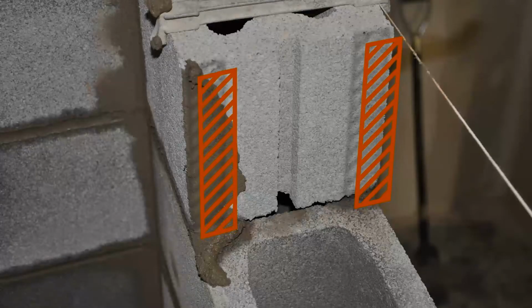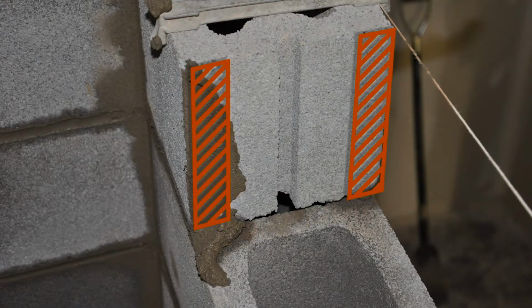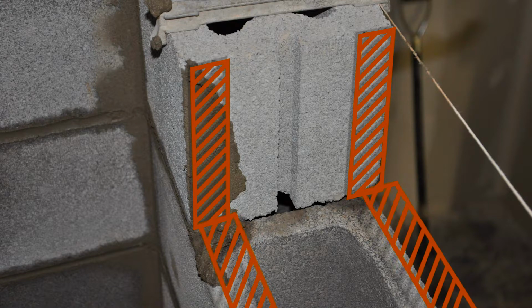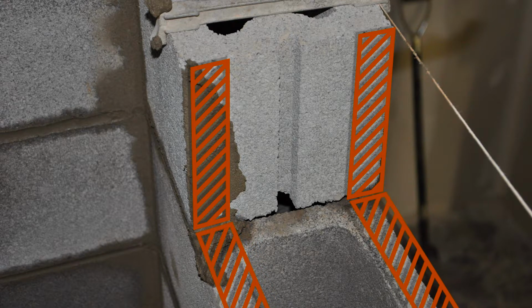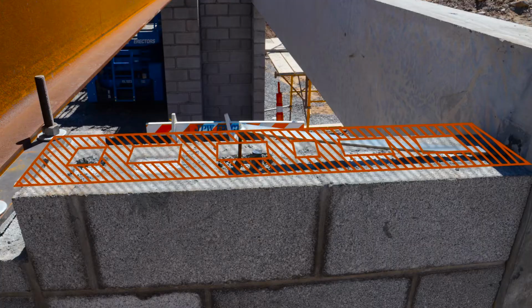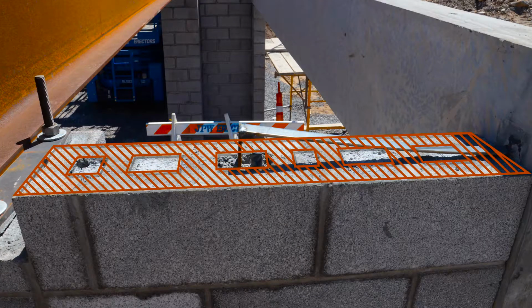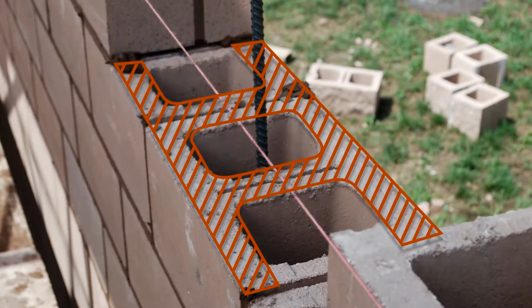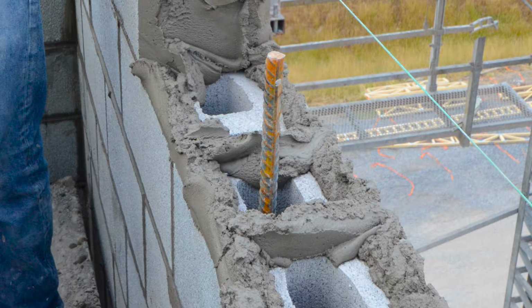A full head joint on a hollow unit covers the depth of each face shell to the width of the head joint, typically 3/8 of an inch wide, the full height of the unit. Further, all web should be fully mortared the depth of the unit to the height of the bed joint, typically 3/8 of an inch high, in all piers, columns, and pilasters, and, when necessary, to confine grout or insulation in the vertical cores. Ensure that vertical cells to be grouted are aligned and unobstructed openings for grout are provided. Grout and reinforcing will be covered in a later learning module.